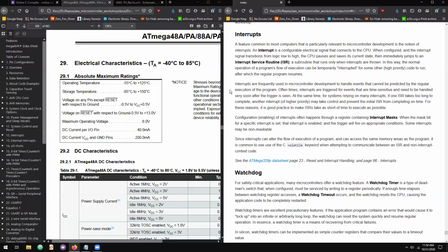The frequency at which you read may be slow enough that there is a significant time delay between when the variable changes or when the pin level changes and when you actually read that the new value is different from the old value. So if you want to reduce that time delay between when your machine can intercept a change that you'd like to detect, you can use an interrupt.